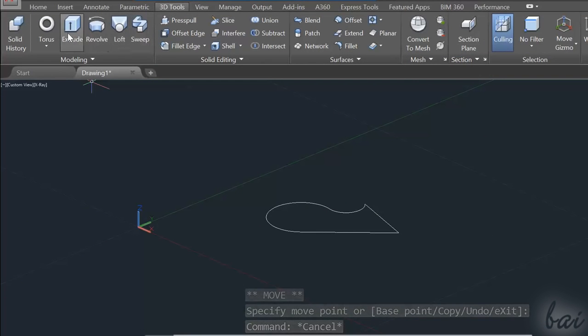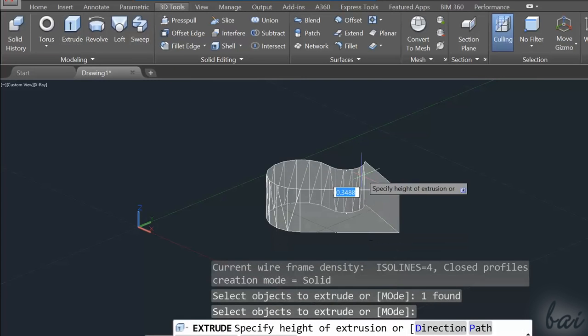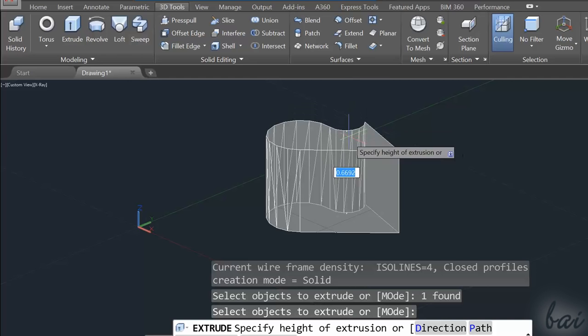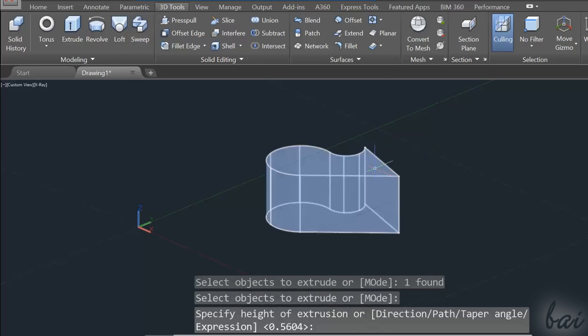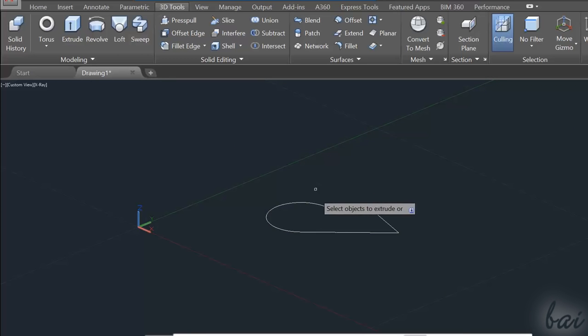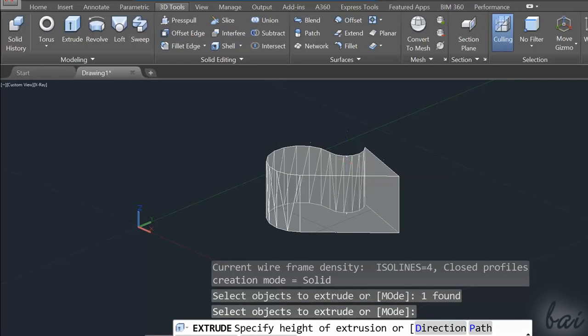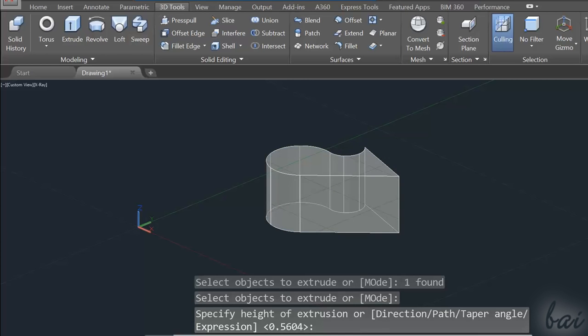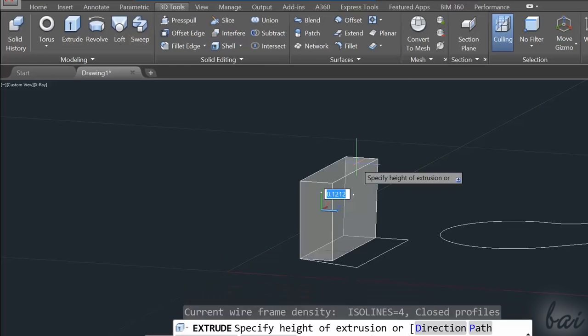The second tool used to build solids from the left is the Extrude tool. This creates 3D objects starting from the 2D objects used as base, by adding extrusion depth along a direction always perpendicular to the base. Select first the 2D object to be used as base, apply with Enter key, and move your pointer to fix the extrusion level. This tool works with any base, even with the ones that are not parallel to the ground plane of the system.